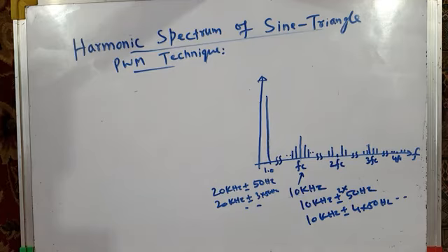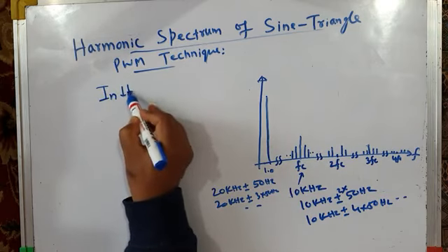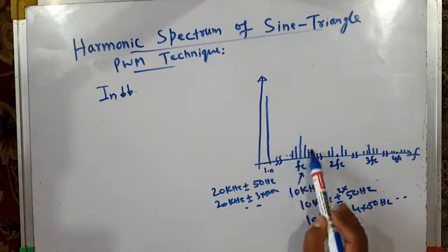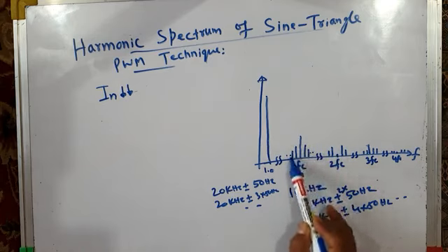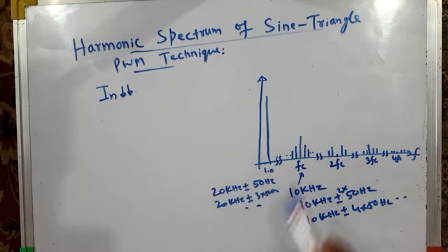And at very high frequency, when these harmonic voltages are applied across induction motor windings, they result in the flow of harmonic currents. But since these harmonic currents are at very high switching frequency, the reactance offered by induction motor winding for these high harmonic frequency currents is very, very large. So therefore, induction motor will result in negligibly small harmonic currents. So even though the harmonic voltages around Fc and its sidebands, and around 2Fc and its sidebands, are significant, since these harmonic voltages are at very high switching frequency, the harmonic currents are negligibly small. So therefore, almost sinusoidal current will be flowing through induction motor winding.